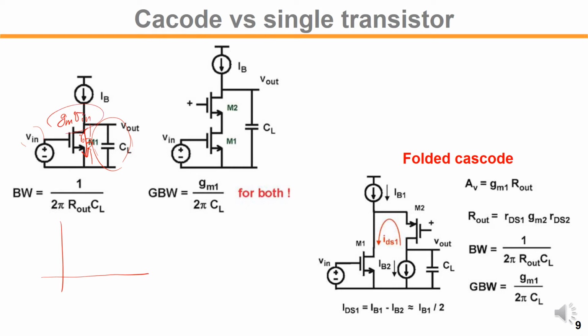Such current will flow through the capacitance, so the output voltage will be gm times 1 over sCL, with a minus sign. This is the AV at mid-band. At low frequency DC, it will be set by gm RO.